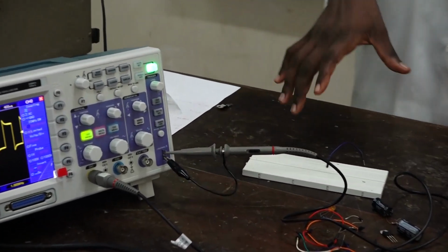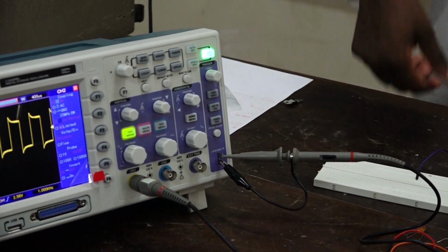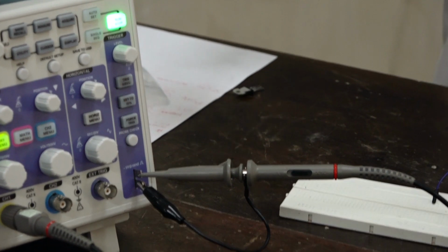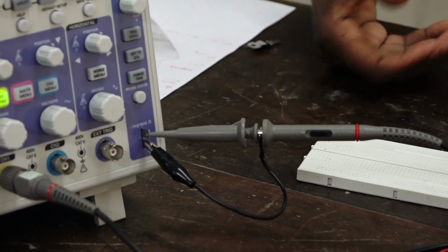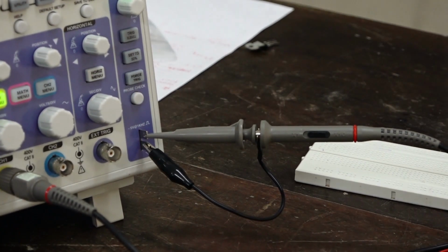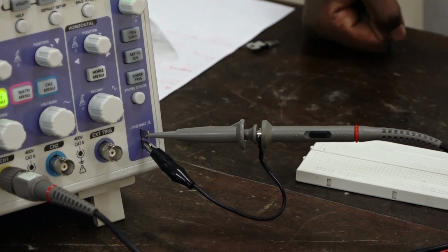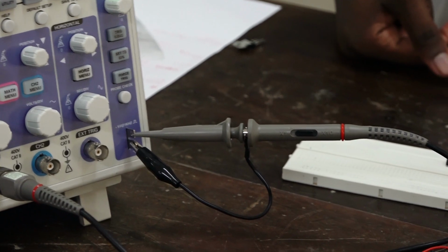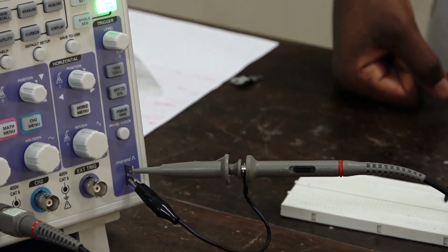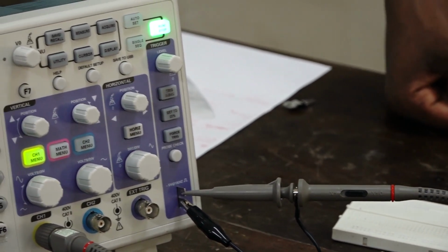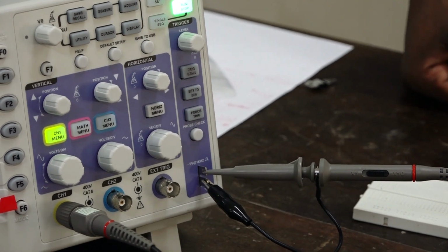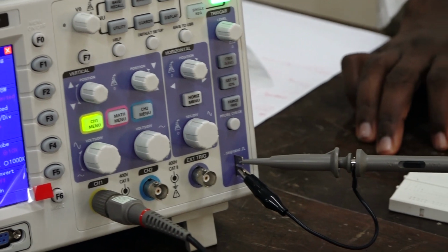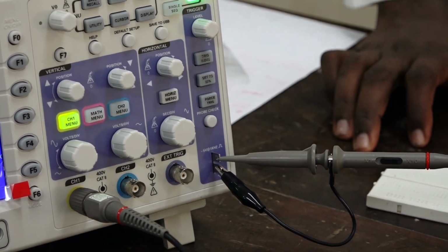I have connected the BNC connector into channel 1, and I'm taking the input from the probe component part of the oscilloscope to feed into channel 1. Are we together? The manufacturer said the nature of that signal will be a pulse. The maximum voltage will be 5 volts. Another thing, the frequency of that signal will be 1 kilohertz.